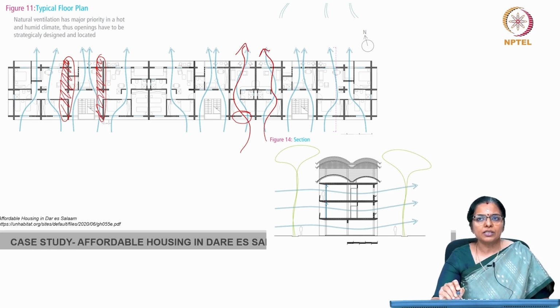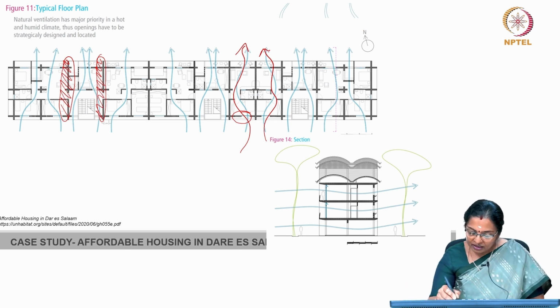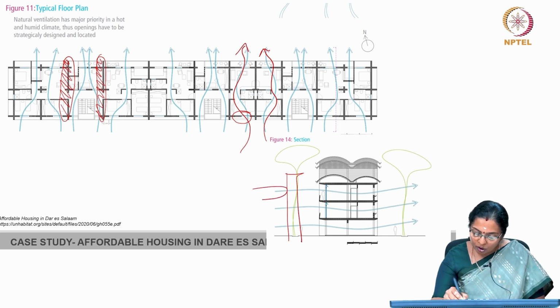The roof features a continuous open air chamber enhancing permanent ventilation, and the open plan layout of the living space minimizes airflow resistance, establishing efficient flow paths for cross ventilation. So, there aren't any hurdles here which will block the wind movement.